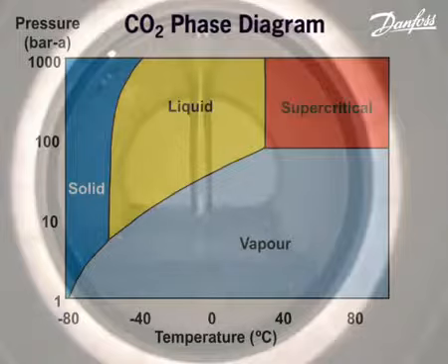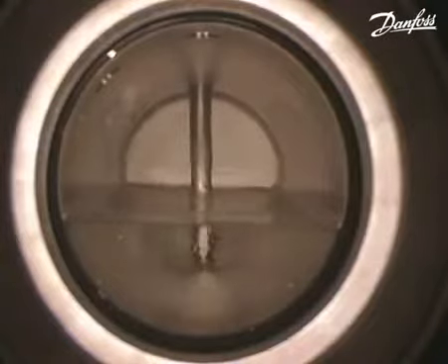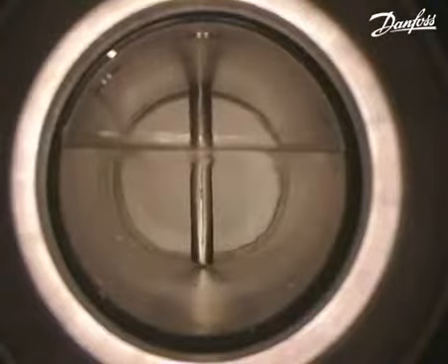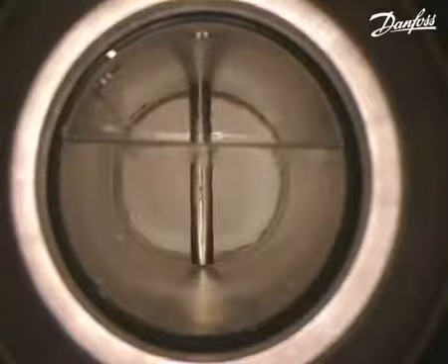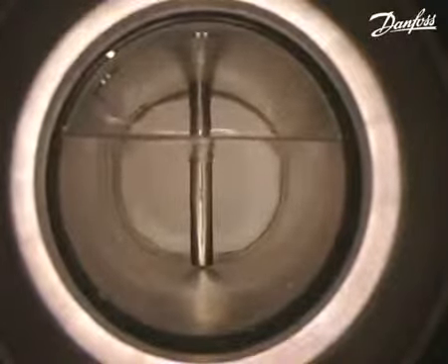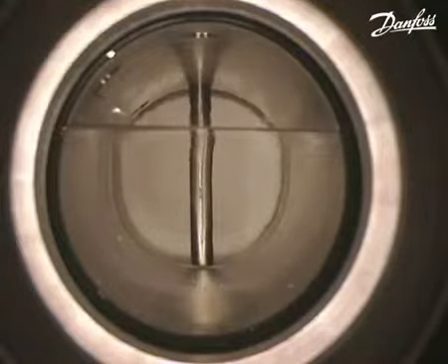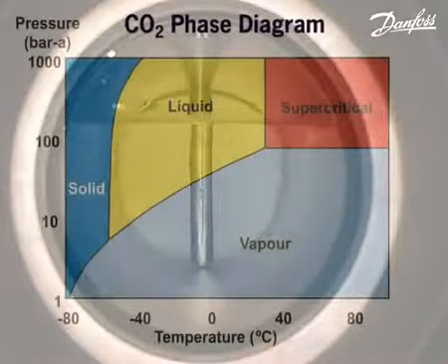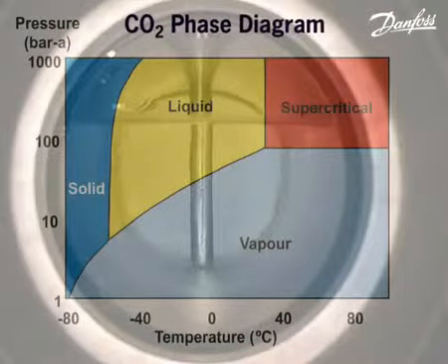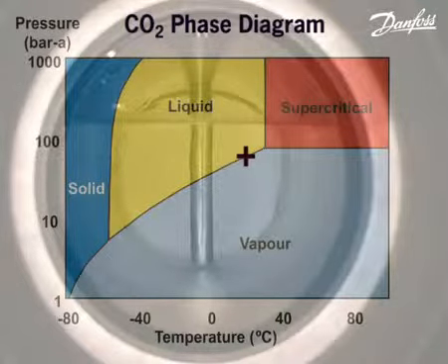Venting CO2 from the vapour phase allows more liquid CO2 to decant from the supply cylinder to the cell, thus raising the liquid level. When the cell is sufficiently full, both the vent and charging valves are closed. When the CO2 content within the cell has settled, the vapour and liquid are in equilibrium. This is represented by the cross on the vapour-liquid line.